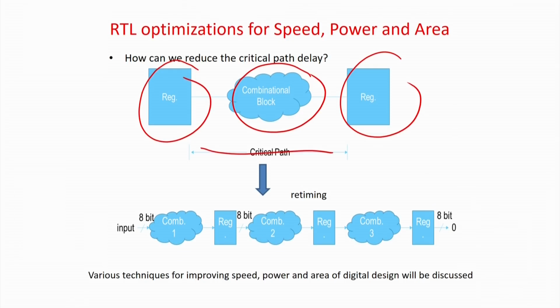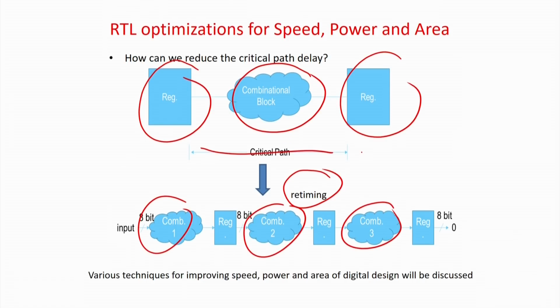In one case we break it up, which is called retiming. You are breaking the combinational circuit into smaller parts and putting registers in between. If the combinational circuit is smaller in size, higher speed can be achieved. This is similar to pipeline architecture. So some lectures will be dedicated to how we can write such circuits. Mind you, these are all parts where the design is being optimized, but because as humans we are specifying the design requirements at the top level, in a high level specification, they are not automated.